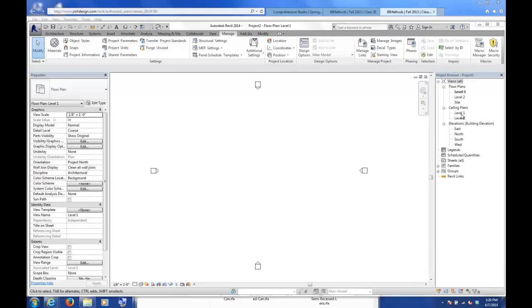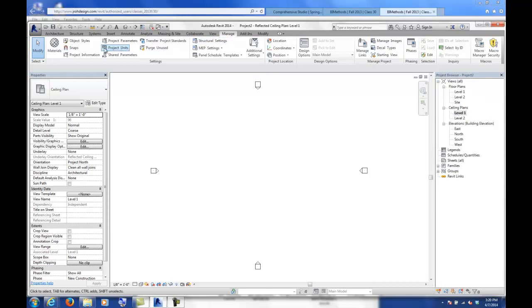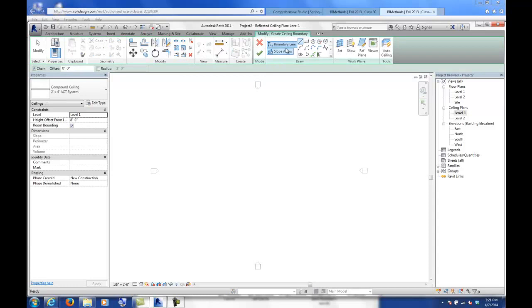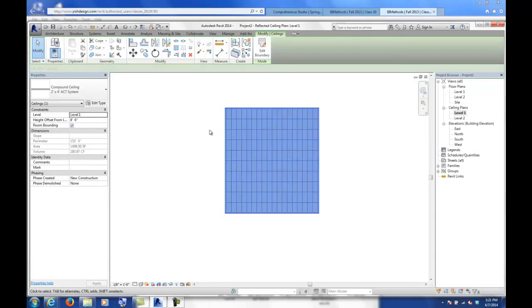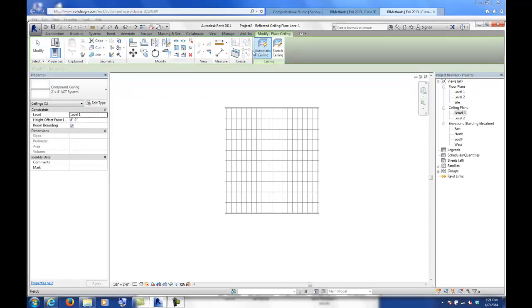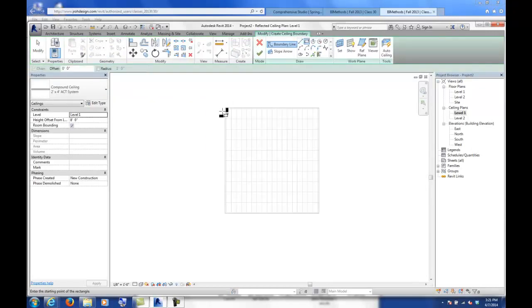And then it's going to taper up. It's like the last 3 or 4 feet. Okay. So if I had a ceiling plan and I go to my architecture, I'll just sketch one right here. So you can do a couple things. I have this flat one. What I would probably do is draw another ceiling that's going to be representing the tapered portion. And so I'd go to ceiling, go to sketch here. Let's say this is going to be my taper right there.